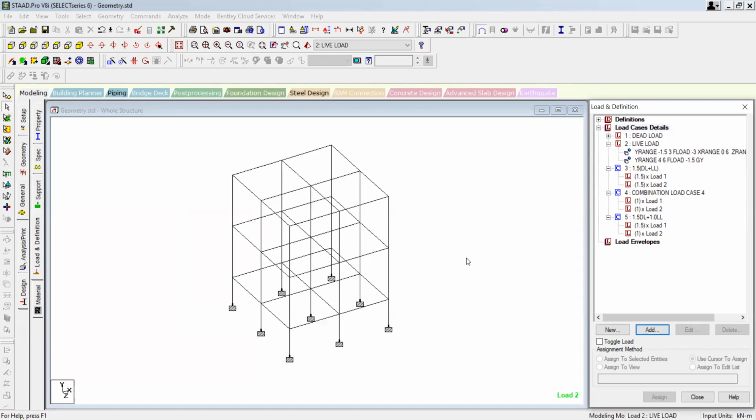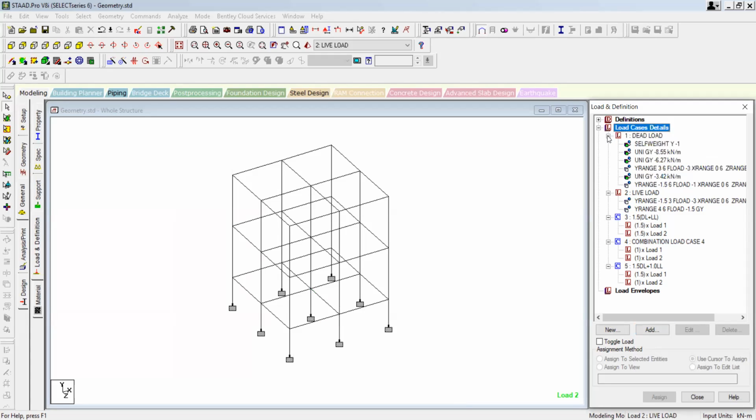So, as I told you at the beginning of the loads, the heart of the structure is load combinations only. You have to give the load combinations properly. If you don't give the load combinations properly, the loading will be acting differently, and the structure will not be stable, or will not be designed for the particular load cases. Okay, now we have completed our main task.